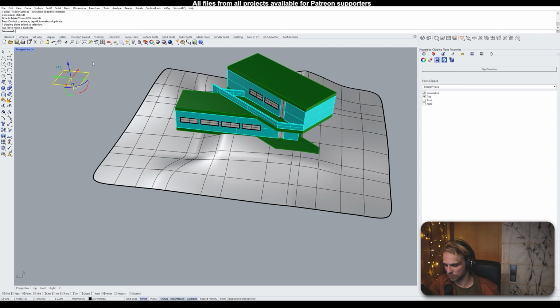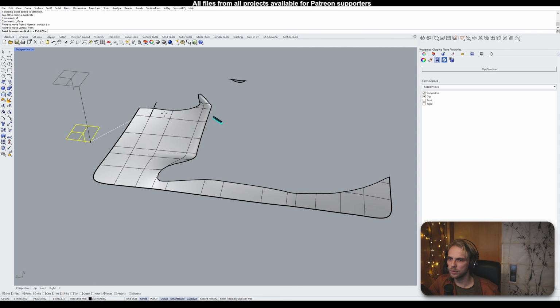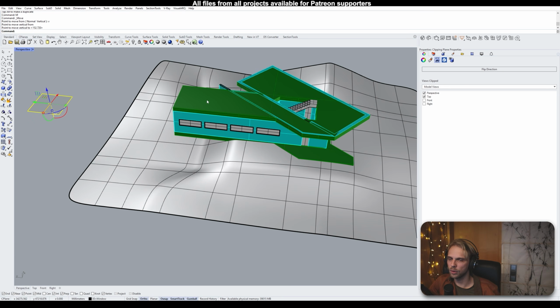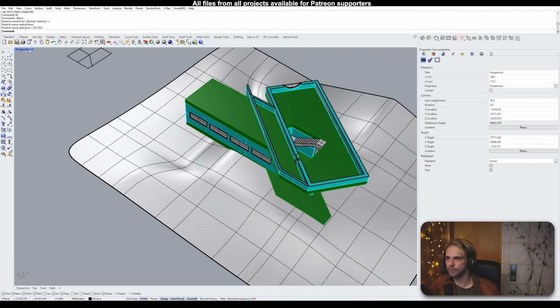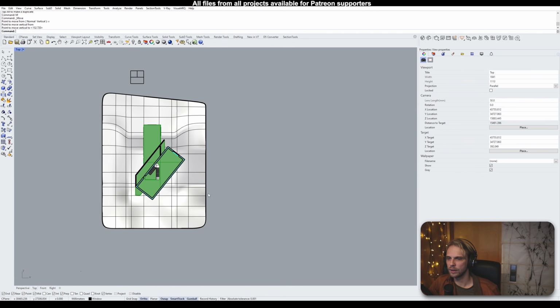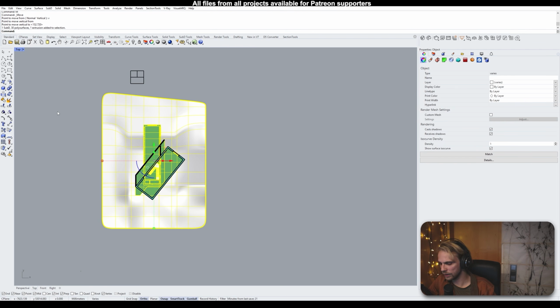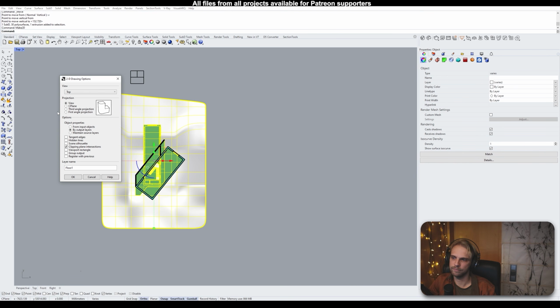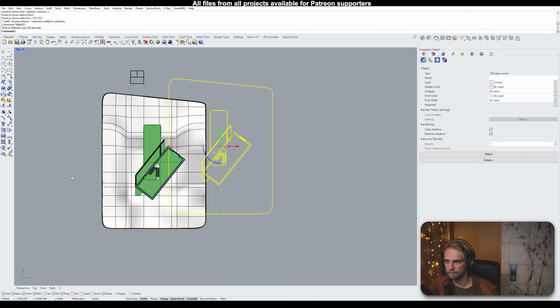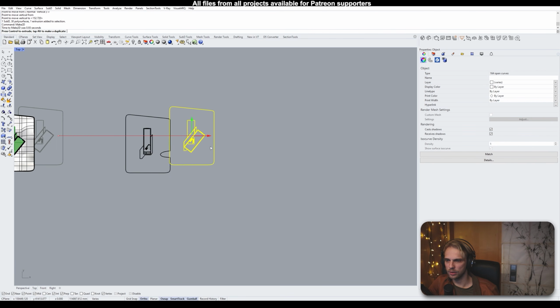Actually, I should probably type move, enter, V, enter, move vertical, and move it until it reaches the top of the second floor slab and move it up by 800 again, so that it clips. Again, selecting everything, make 2D, floor 2. All of the settings are the same. That's our second plan.